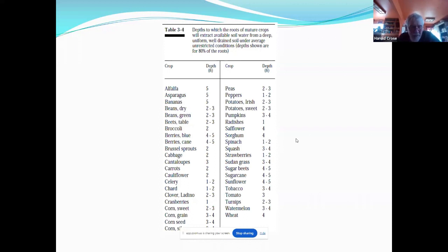You know, they're typically set up either for a wheel line on 24-hour or 12-hour sets. If they're on 12-hour sets and there are 60-40 spacing, on 24 hours, they only cover 60 feet. If they're going 12 hours, they can cover 120 feet in 24 hours. So that gets back to that irrigation frequency thing.